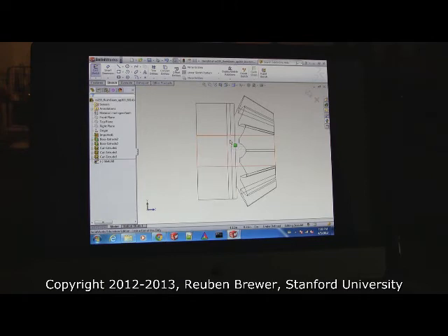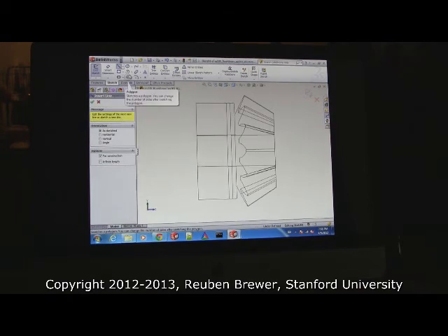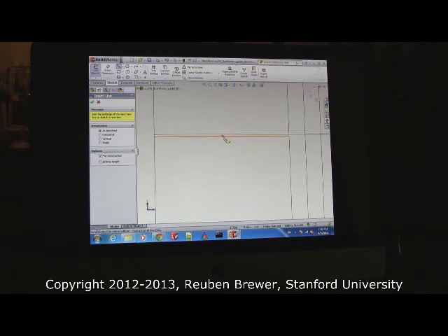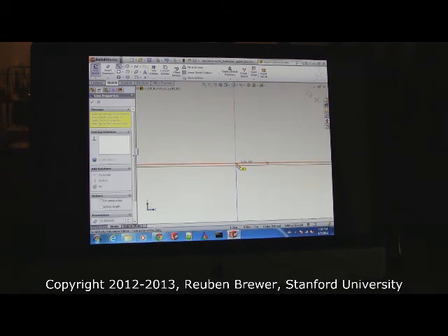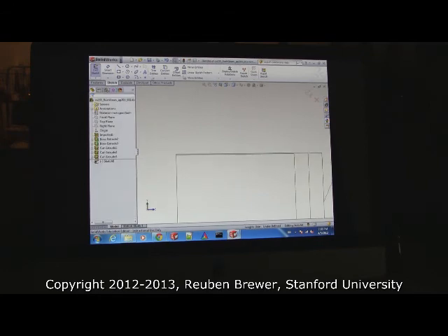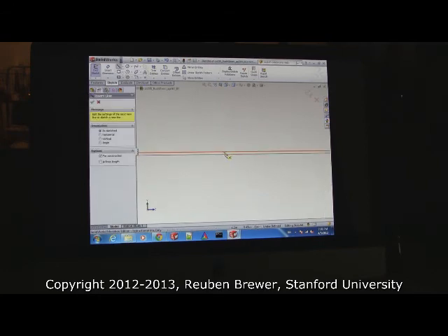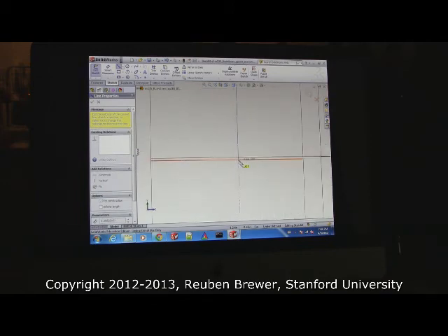We all good? Okay, now take a construction line. See this right here? I'm going to zoom in. See that thing right here? Put it there. Put the other side over here. On the very outer one. So I'm going to do it again. Take a construction line. Zoom way in, because we're looking at multiple surfaces here. Take the outermost line and put it dead center, and it will snap to. And then zoom out and zoom in back over here.